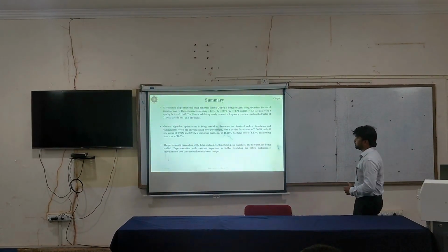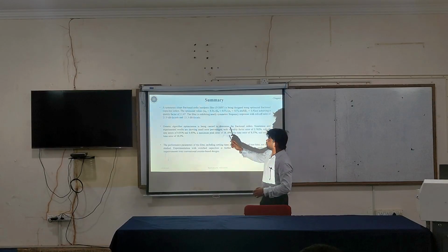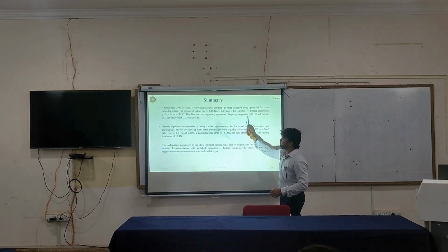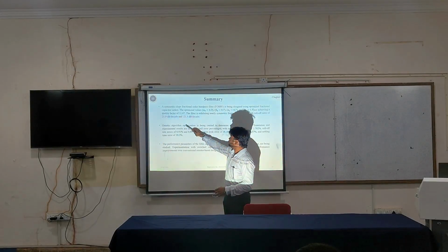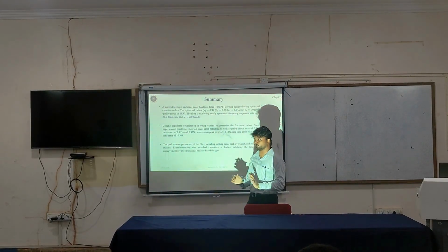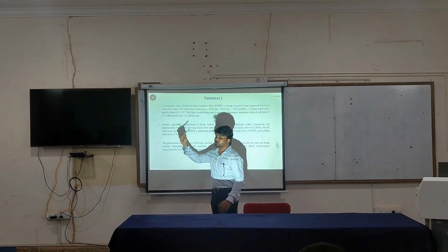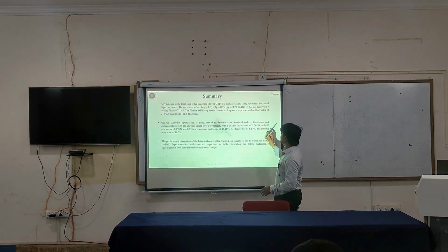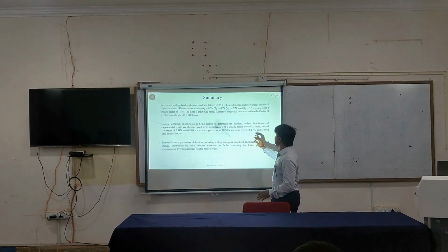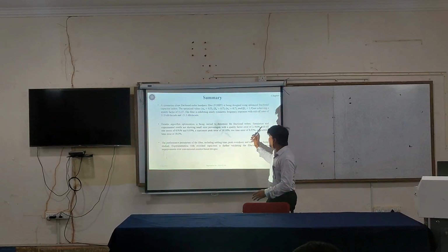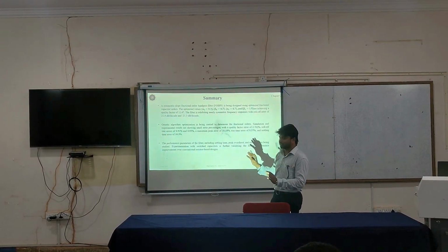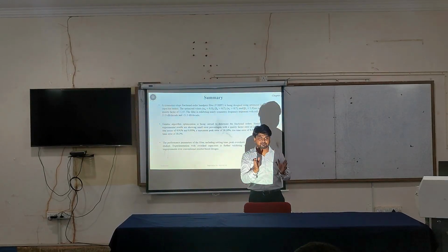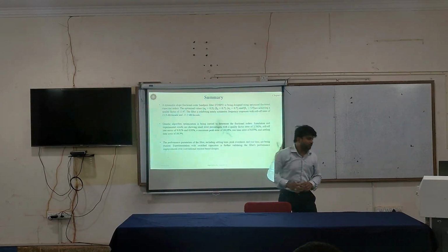Now, in this chapter, we have seen that at optimized orders 0.3, 0.7, 0.7 and 1.9, we achieved a quality factor of 11.47. The filter achieves a nearly symmetric slope response of plus 21.9 dB per decade and minus 21.3 dB per decade. And here, the quality factor, the roll-off rate, the maximum peak and the rise time all held minimum error percentages when comparing the experimental with the simulation part.